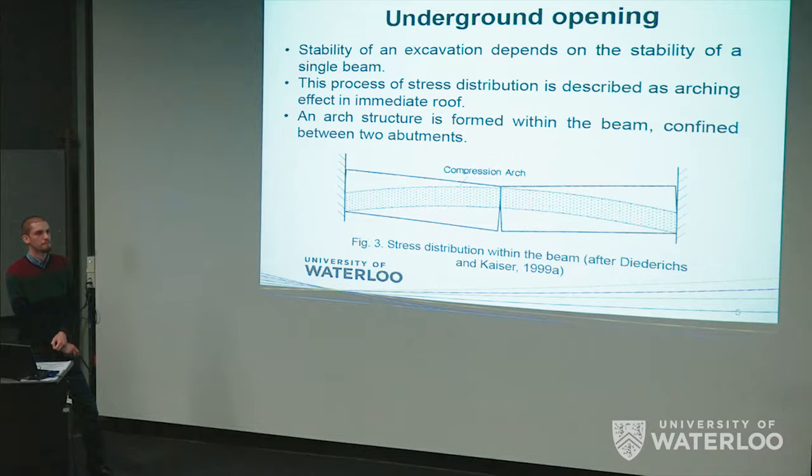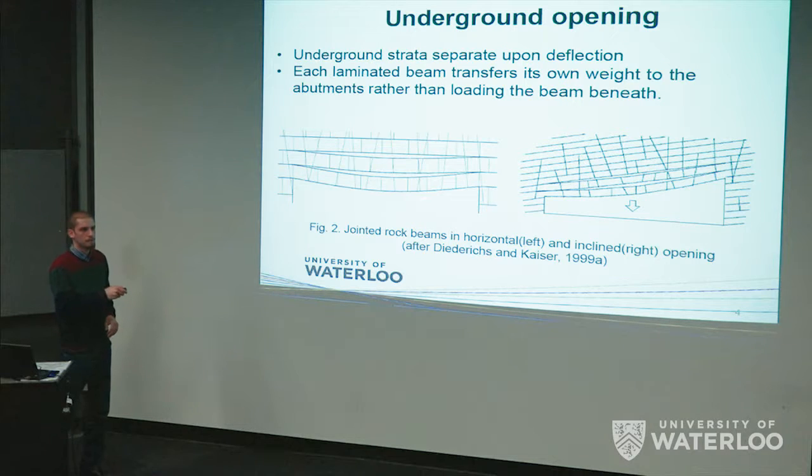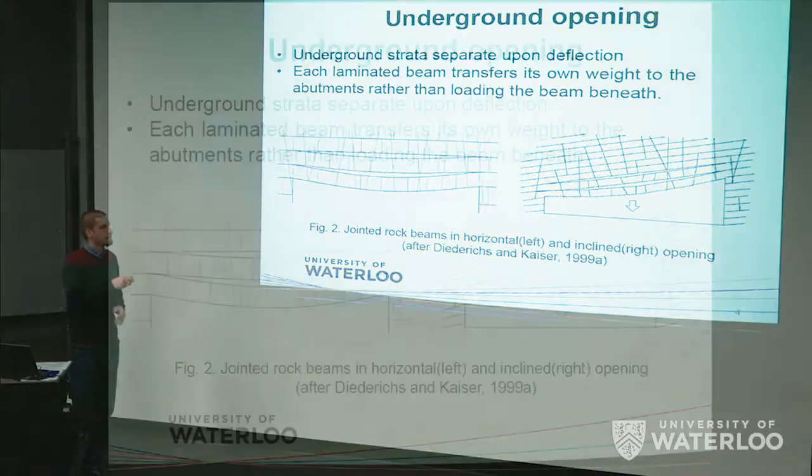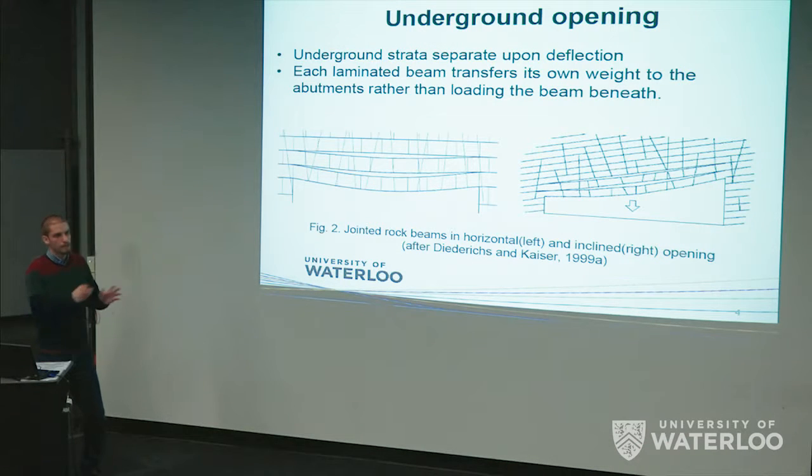All right. Okay. Yes, it's a really good question. I can answer this question in different aspects. One thing is that I said over here that we have these layers up and down at the top of the cavern, and these are fairly separated from each other. It's also experimentally observed that this would happen for a cavern roof. So it's a simplification, for the sake of simplification, that we have just one layer at the top. It's called the immediate roof, and we can analyze this method.